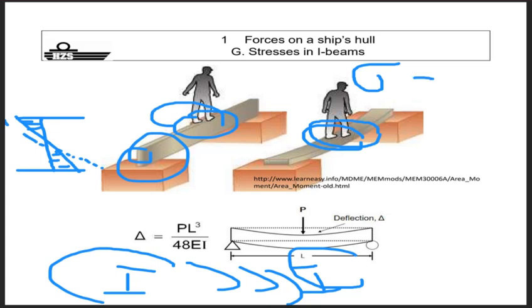So somewhere soon in your formula, you will have an I below, because if I is big, stresses are small and vice versa. What else might be a predominant factor in your stress level if something is subjected to bending? Bending leads to compression and tension. What is another factor, do you think, that might be important?